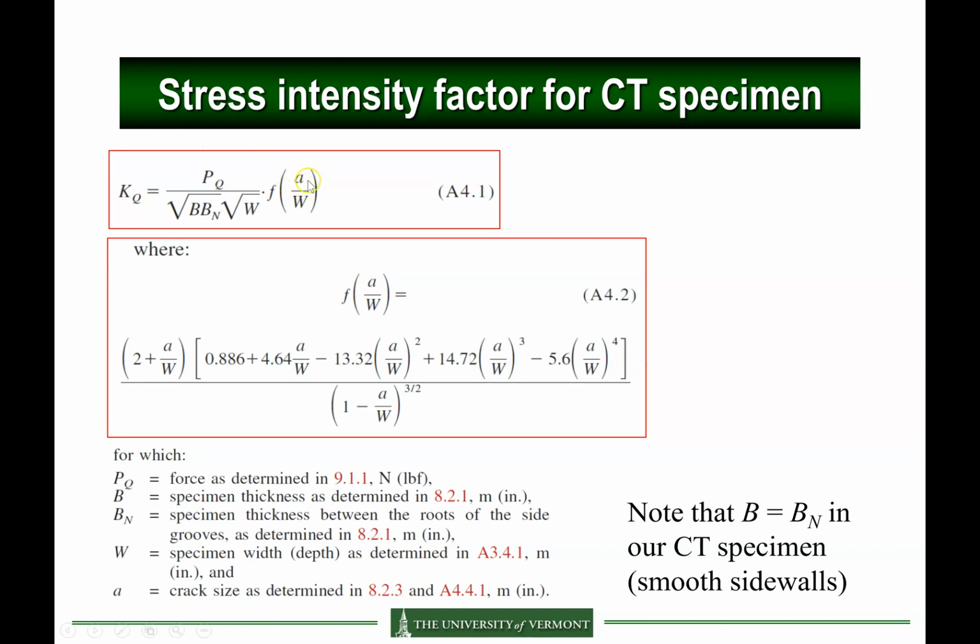So we'll be able to measure A after the test is completed. Okay, so the technique is really finding P, and then after the test measuring A and plugging this into this equation to find the fracture toughness K1C.